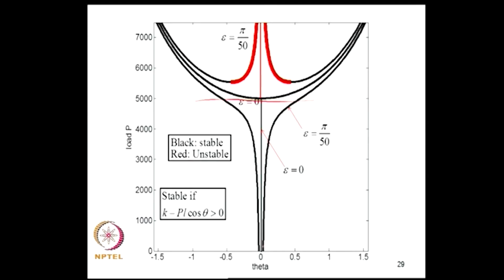As you come in an imperfect system, or even a perfect system, as you come close to the critical load of the elastic, linear system, the rate of change of deformation is rapid with increase in load. That is how the kind of remnant of instability is manifested here.